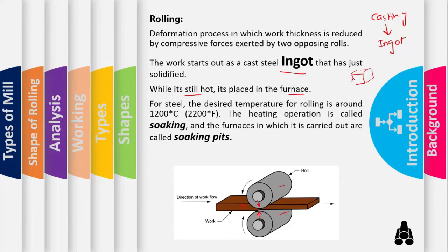What is the purpose of putting this in the furnace? Once it is placed inside the furnace for a long period of time, it will have a uniform temperature throughout, so the plastic deformation that is produced will be uniform in all the regions of this workpiece.